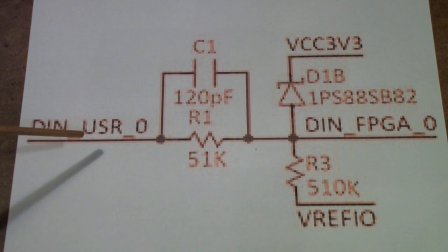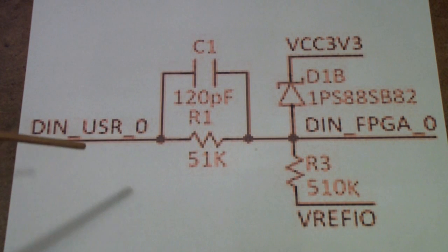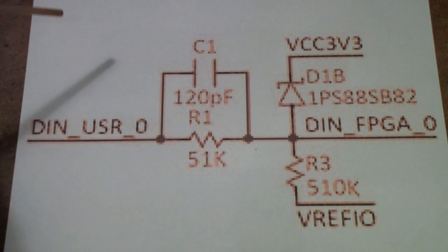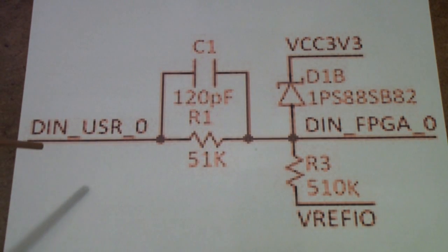But the largest logic level that it will reliably work with is 5 volts. So it will work with TTL and TTL CMOS logic. It will not work with higher voltage logic. That exceeds its capabilities, and you would have to use some kind of input divider circuit, which is, of course, completely separate from the Digital Discovery.